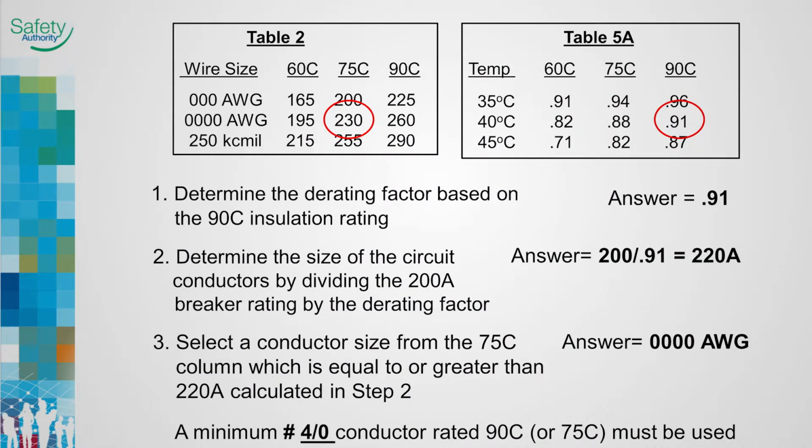Here we have provided examples from Table 2 and Table 5A. In accordance with the wording of 4-006, Subrule 1, the size of the conductor, including any relevant correction factors, must correspond with the maximum termination temperature marked on the equipment.